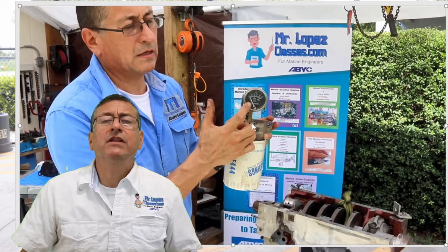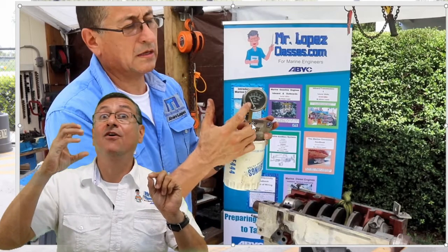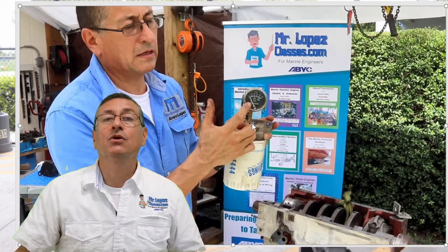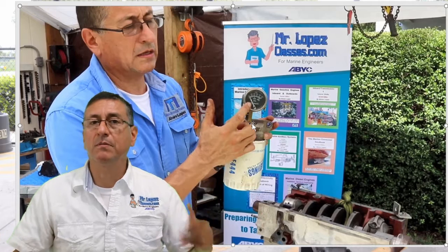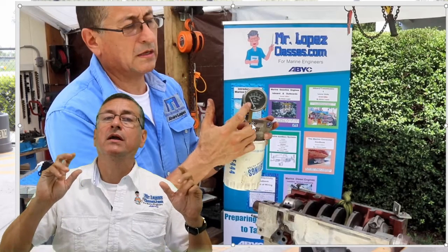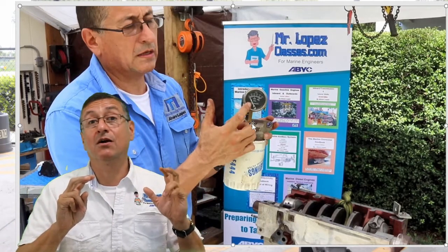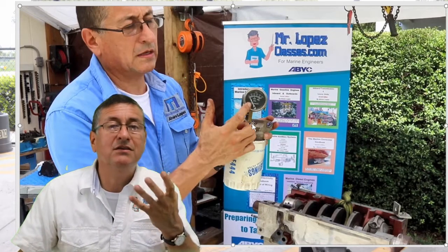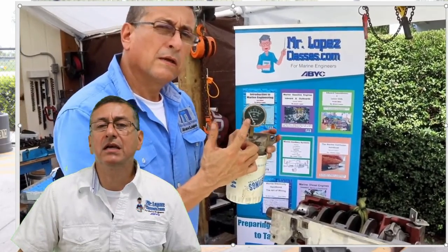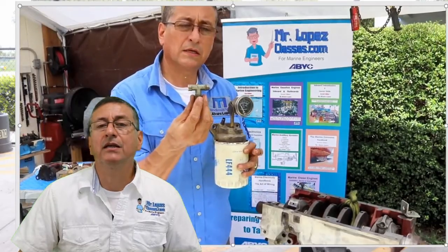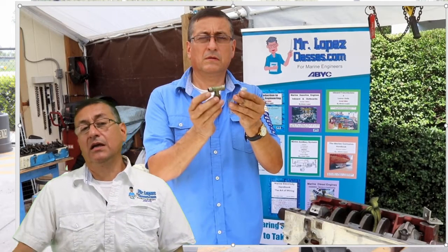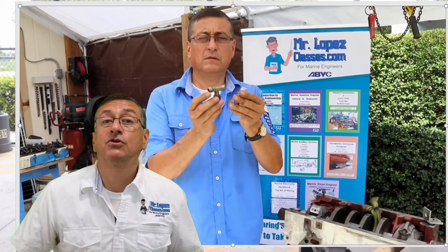Or you can install a T over there and install the oil pressure switch and the oil pressure sensor. Right now we are going to talk about that switch and sensor and what their function is. You remember we did the harness in our electrical course, and now we are going to refresh the moment where I install the oil pressure sensor and the oil pressure switch in the engine. Right now it's easy for you because you understand what happens with the movement of the oil. Yes, at that point you can install a T, a T like this one, and on each end of the T you install both sensors, the oil pressure sensor and the oil pressure switch.